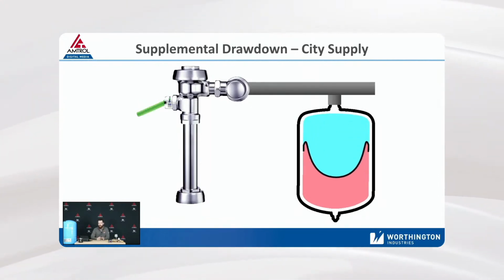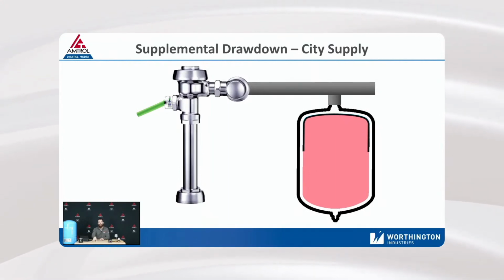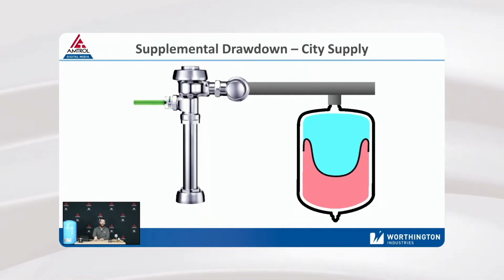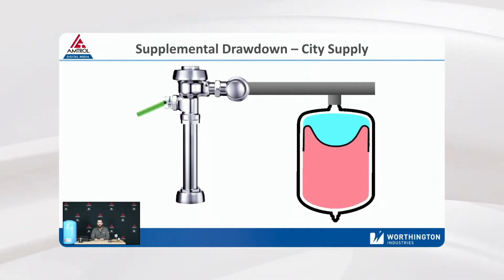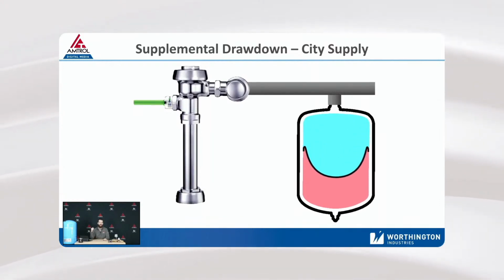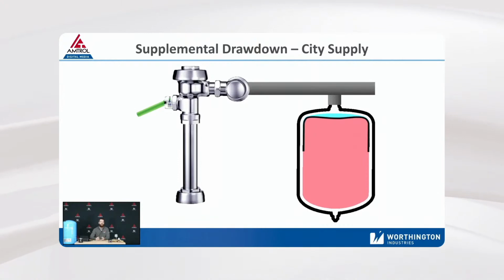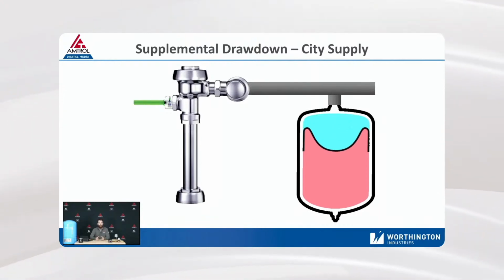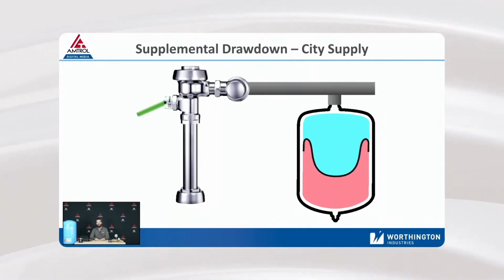So it's similar to how normally we size a pressure tank, but you could tell it is different. There's a different way we have to look at it. There's different questions we have to ask, and the pre-charges aren't just going to be 2 pounds below cut-in, because on a city system there is no cut-in. There's a lot of different ways to look at it, and we have to make sure we're handling it right.